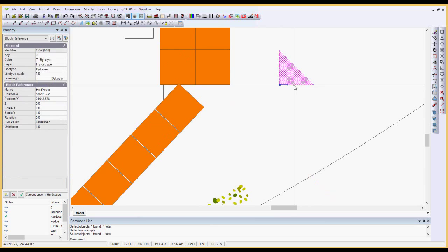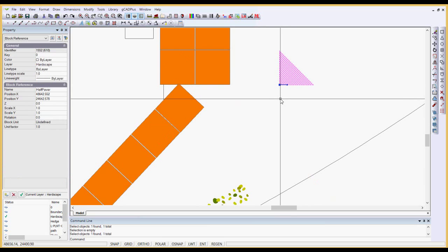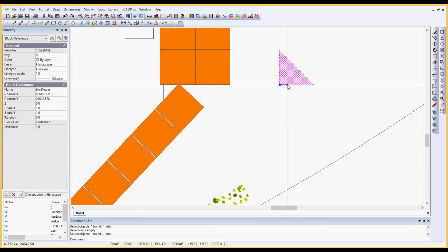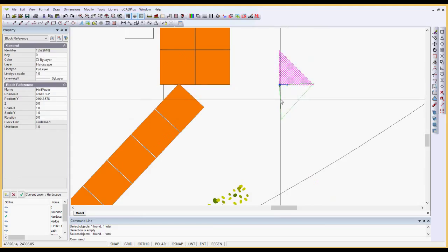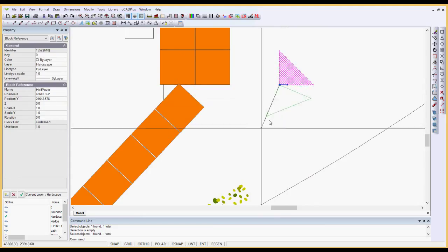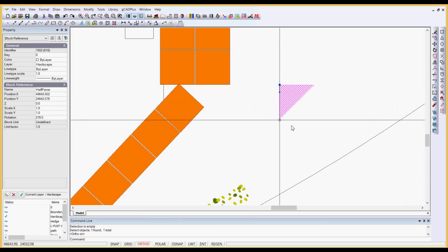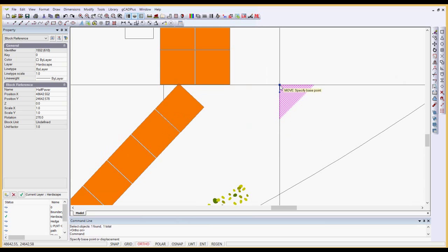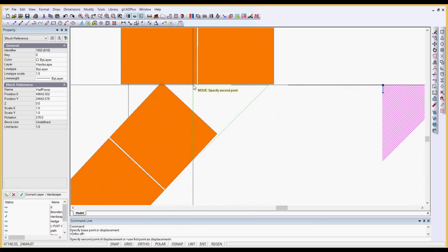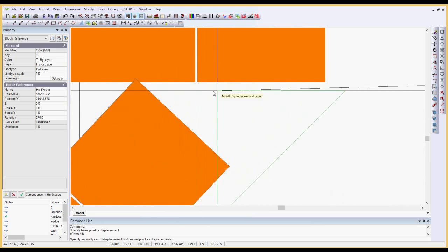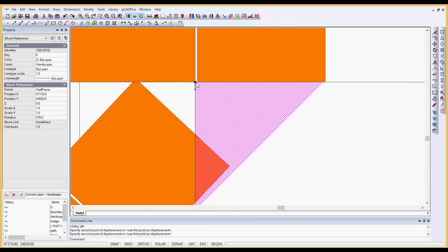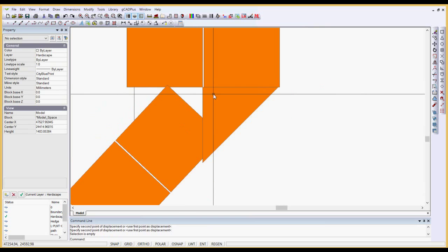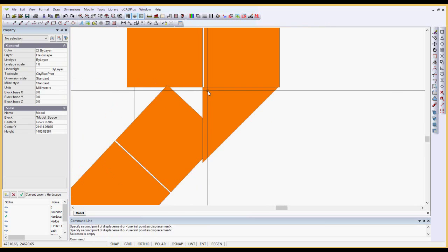What I'll now do is rotate that paver so that it fits nicely. If I put ortho on now, I can get a precise rotate, and now I can move the base point there, and let me take ortho off, and I can move it and put it in position there. So I'll see if I can pick the end there, and I can. So now my half paver sits quite nicely in position.